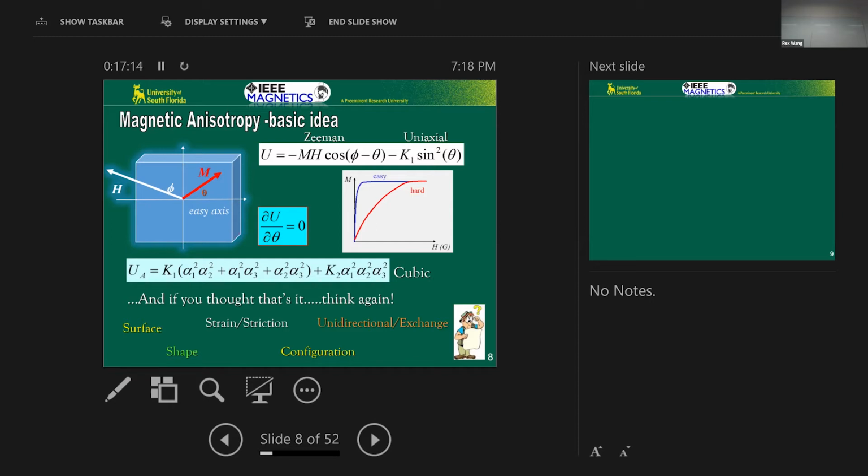This is very important for the spintronics community. Almost every spintronic device that you can think of, MRAMs, of course, magnetic random access memories, they're based on this antiferromagnet interface. What happens if you put an antiferromagnet and ferromagnet together at the interface, because of the difference in the anisotropy, the spins of the interface get pinned. And basically, that can be used for changing the shape of the hysteresis loop, like changing the coercivity, and also shift the whole loop. This is called exchange bias. Okay, by applying magnetic field, you actually shift the whole hysteresis loop, and this is behind the so-called spin valves, which are basic elements for spintronic devices. It goes to the MRAMs, for example.